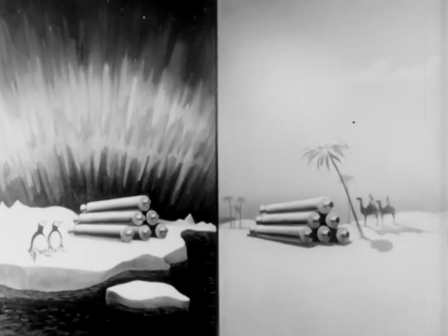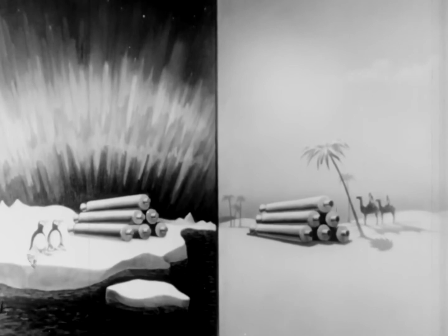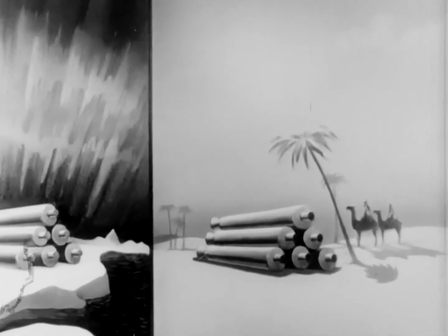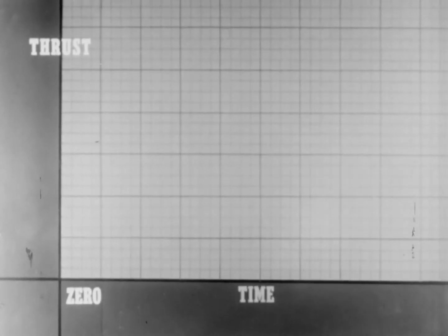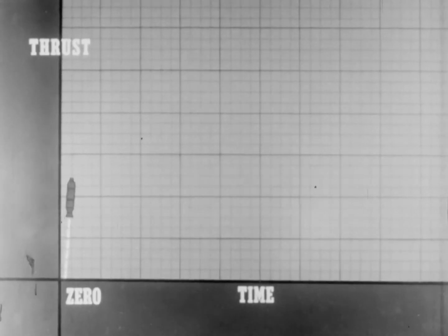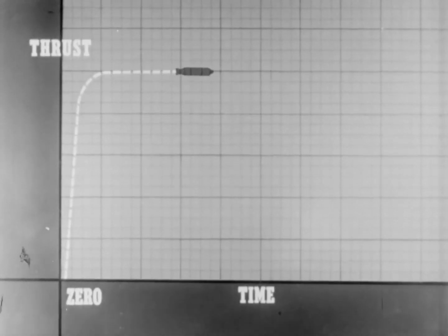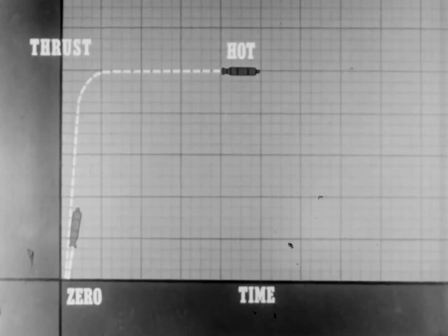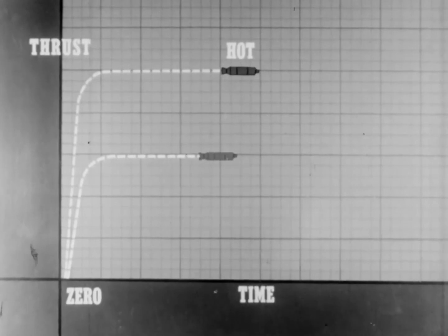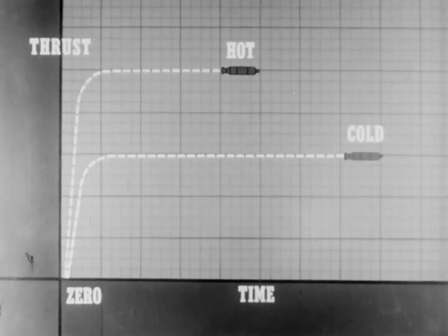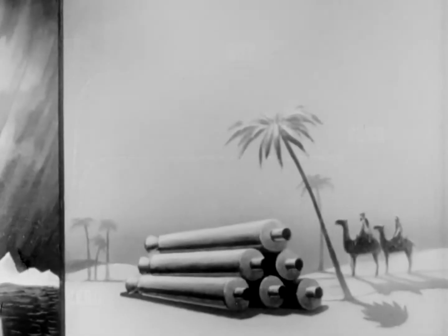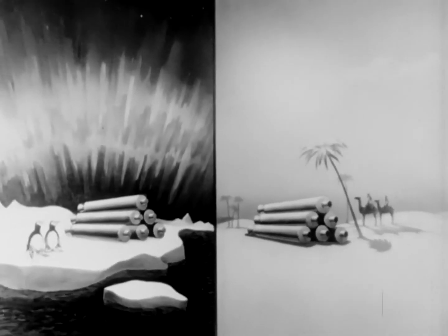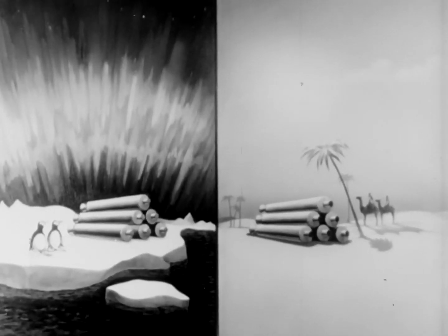Even though most solid propellants will store for short periods, under extreme climatic conditions, such temperature variations will have a definite effect on their amount of thrust and the length of time they will burn. Propellants which are heated before igniting will burn rapidly, giving greater thrust, but shortening the total burning time. Cold propellants, on the other hand, will burn more slowly, giving less thrust, but will burn appreciably longer. Neither of these conditions are liable to create any hazard as long as temperatures are within design limits.